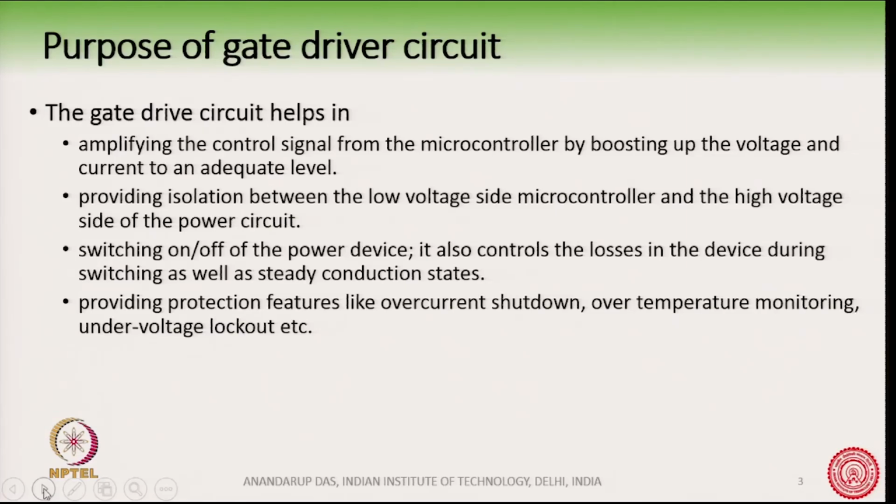And often the gate current or the gate charge required by these devices is quite substantial. Many times we see, for example, that the gate current required by an IGBT or sometimes a silicon carbide MOSFET can be several amperes, 2-3 amperes; the peak gate current can reach such high values.